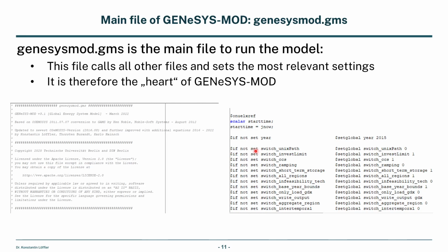Then you can set the values for the switches exogenously, outside of the actual GAMS runtime, for example in a batch file or some job file on a Unix cluster, and then, for example, calculate different sensitivities by doing so. If you don't give it a value from the outside, then it will refer to the value that you give it on the right hand side here.